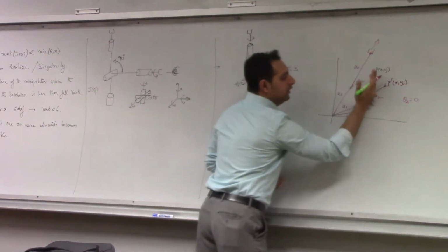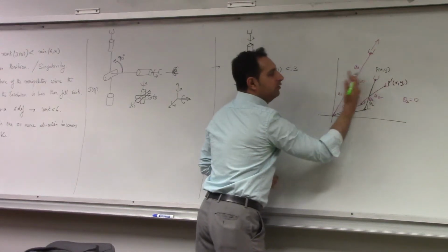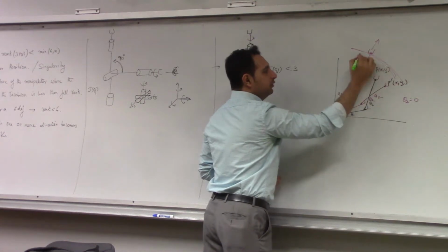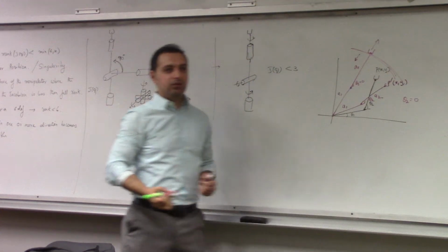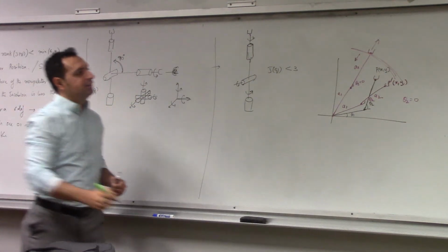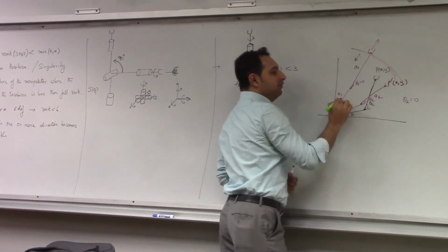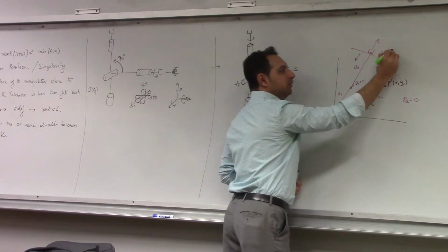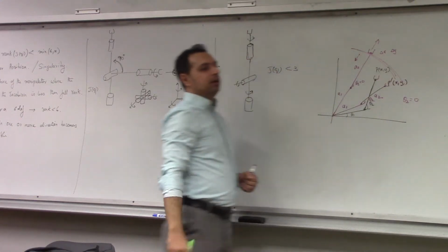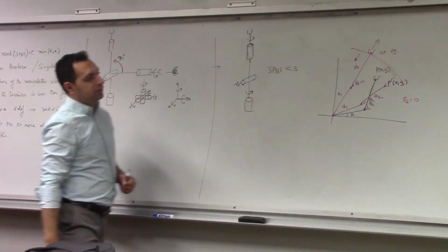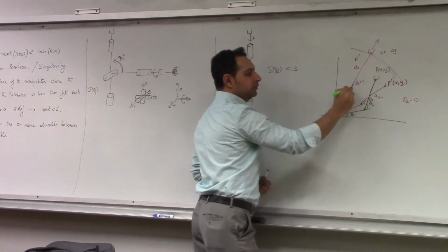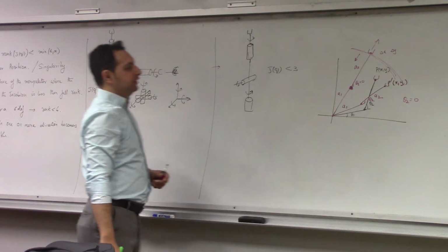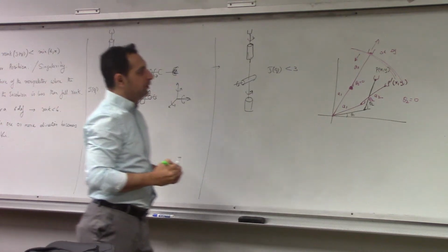When you are here, in this direction, you can move further or you can move inward. In this case, it's at the boundary. The only option is to move inside. You cannot move outside anymore. So moving outward is limited. You can apply an infinite force, but it will not generate even a small change in x or a small change in y. Nothing can create a change in x or y in spite of applying any force or any torque you want. If it's a revolute joint, it's a torque. If it's a prismatic joint, you apply forces.